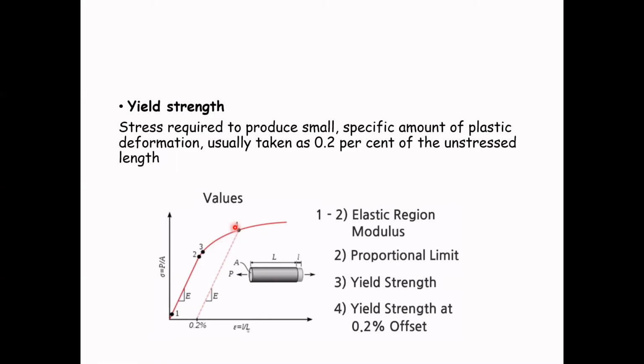So where can we find the yield strength of this particular material? To determine the yield strength, engineers standardize the method by picking one point in the yield region, specifically a value along the strain axis here, rather than taking a point and drawing it straight down.